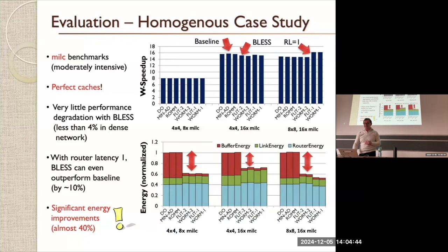But you'd get significant energy savings. So if you look at this picture over here, what should I look at over here? Essentially, these are the bufferless networks over here. We can reduce the buffer energy significantly. Link energy actually increases, because now you have more links that are being traversed, right? Because you're actually using more of the link capacity. And the others actually are kind of similar, but they increase slightly. So because you reduce the buffering energy significantly, you have an overall significant energy savings.